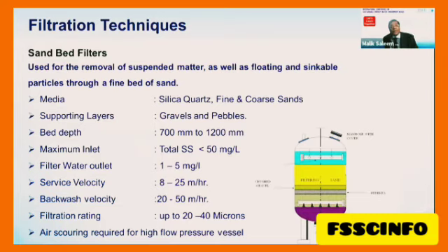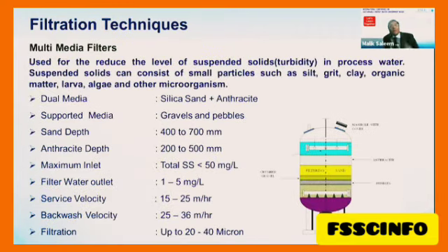I will close. This is information about the sand filter, how to design the sand filter, and you will get the idea of the multiple layers there, how much velocity we have to cap and what size of particle they remove. And this is a multimedia filter. You can see it has multiple media that depend upon the application, on what we have to do with it.